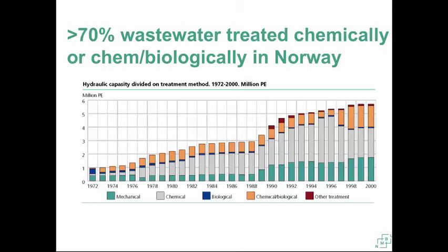And then it is important to understand what happens with the reduced temperature. When the temperature is going down, what could be the impacts? As Pernilla said, when the temperature is going down, the water gets more viscous. When the water is more viscous, then the settling process gets retarded.